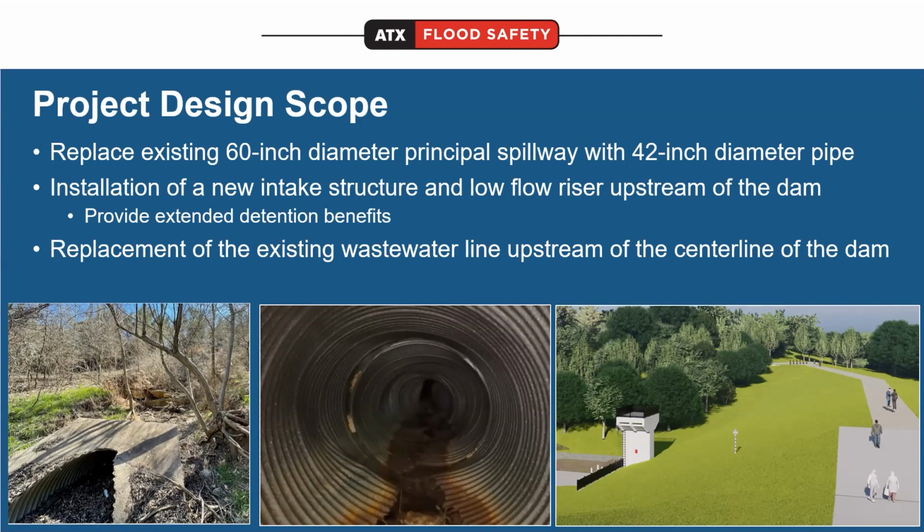We're taking out the existing corrugated metal pipe and replacing it with a 42-inch diameter reinforced concrete pipe. So it's a more durable type of pipe. We no longer use corrugated metal pipes in dams because they don't last long and they get deteriorated, as you can see. So we're installing that new pipe, but we're also installing, if you look at the picture on the right, that vertical white structure, that's a riser intake structure.